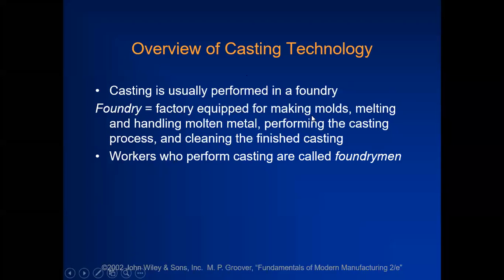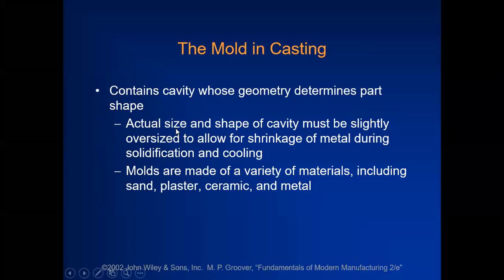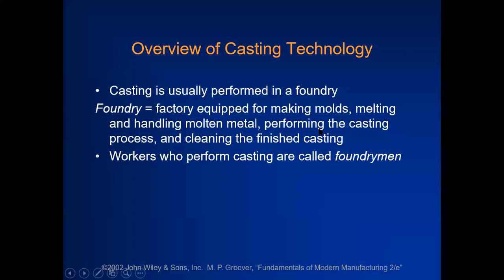Factory equipped for making molds, molding from sand or any other material, just like ceramics. Metal melting of the solidified scrap pieces of the metals, then handling of the molten metal from the furnace to the mold, performing the casting process, meaning letting the molten metal solidify, breaking of the mold, then cleaning and finishing the casting.